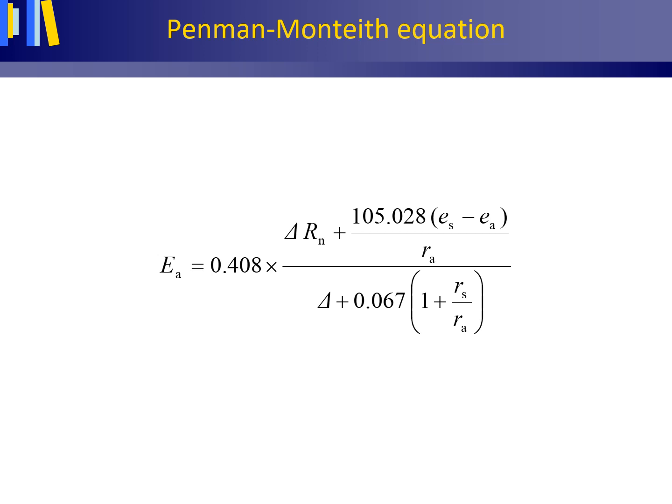The Penman-Monteith equation is shown here, named after the work of the British physicists Penman in 1948 and Monteith in 1973. It is a physically based method for estimating the actual evaporation EA, or under unstressed conditions the potential evaporation EP, based on both the energy balance and atmospheric demand.